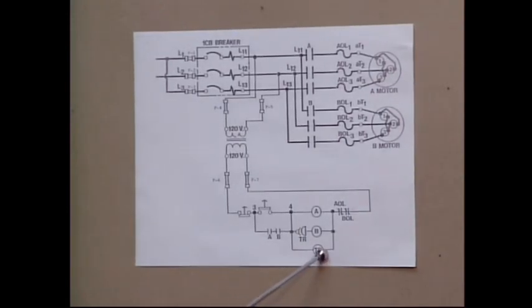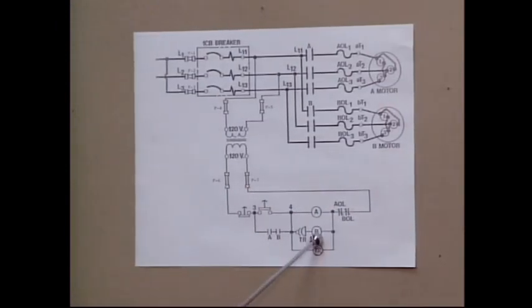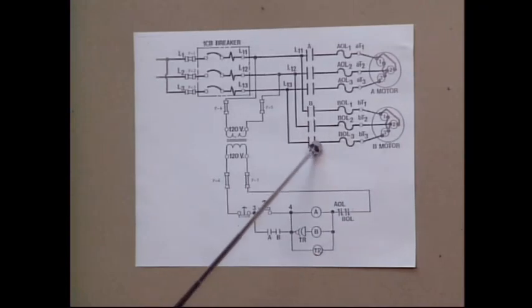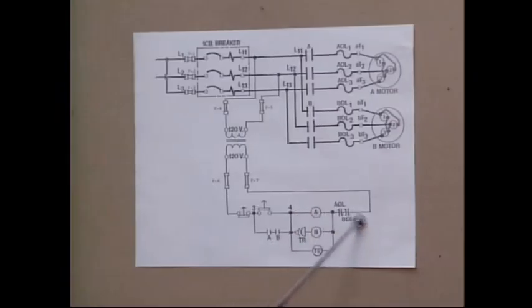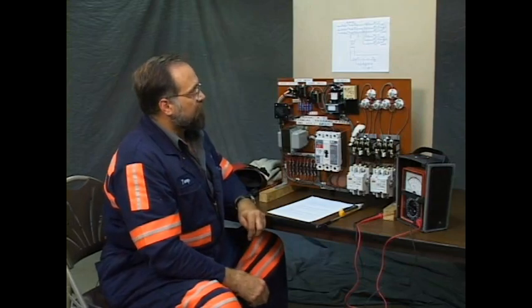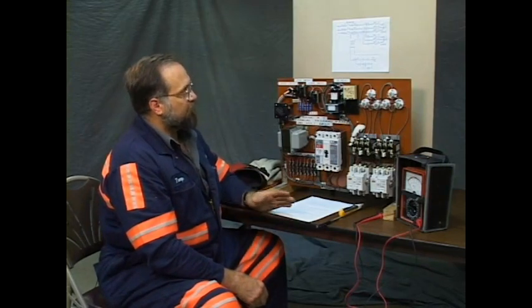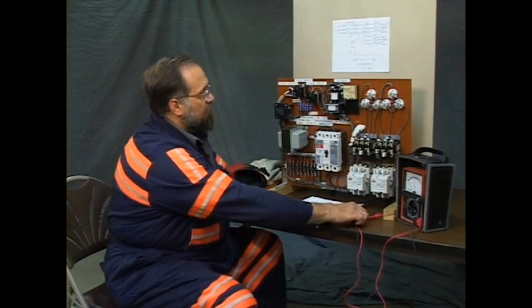TR has timed out after 1 second. These tips close. This mercury tube is now made. B should receive power, follow the same return as A, and B should pull in, close these tips, and have this motor. Well, the A part of that circuit's working. The B is not. There's a timer involved. The timer has to operate before B can work. And the mercury tube, you know.